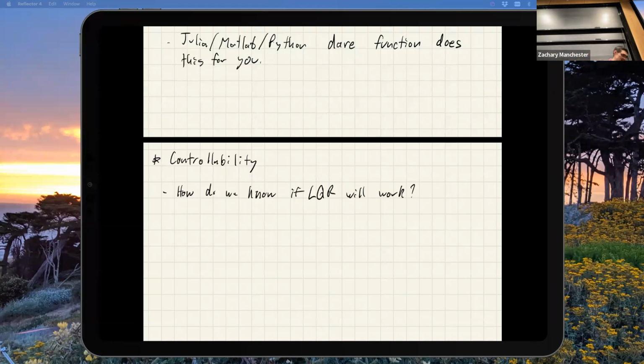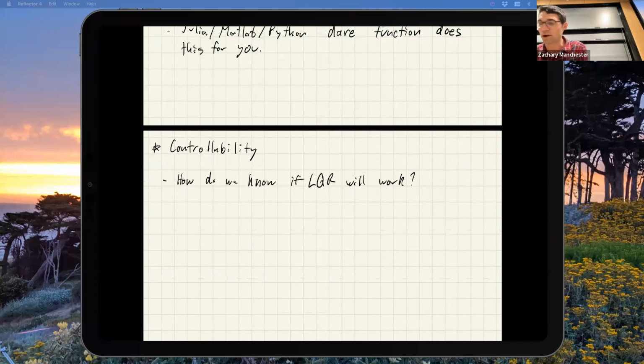The classic example is if I have a humanoid and I straighten the knees out, you get singular Jacobians when the knees are straight. That can make you uncontrollable. So you can have systems where, for certain values of the configuration, they become singular and you get an uncontrollable system instantaneously when you linearize. So this is something that comes up that you have to worry about quite often.